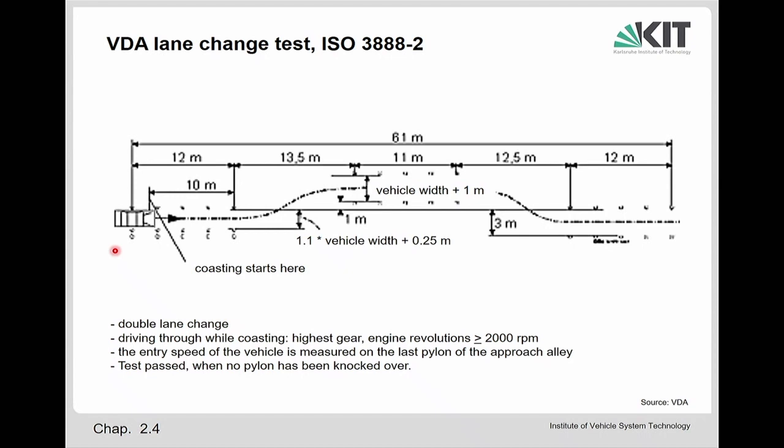And so then I go into one curve. So I will have a very high force on the front outer wheel, a very high vertical load in the curve. And because I have a very high load on this specific wheel, a very high friction force can be transmitted. Yeah?